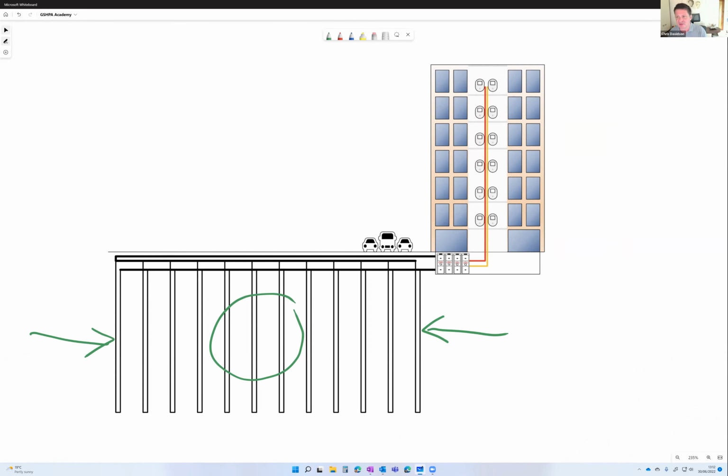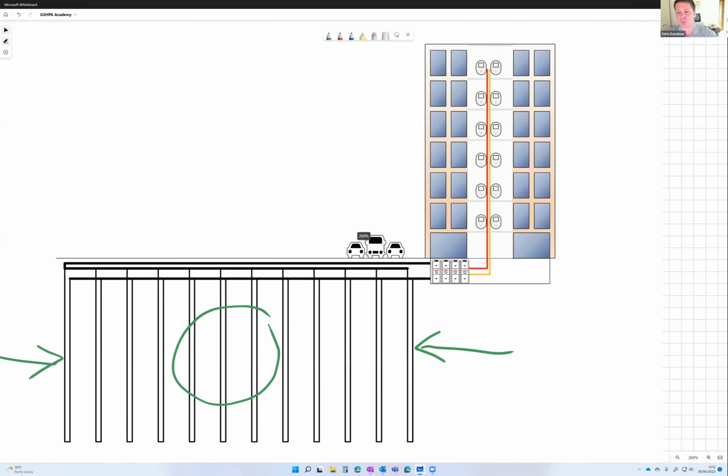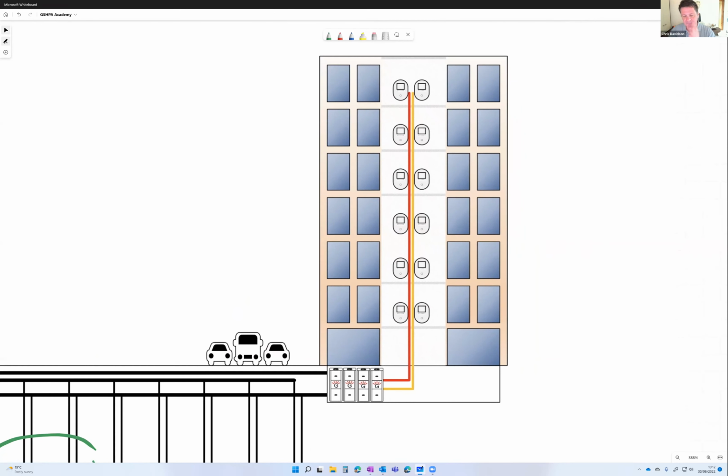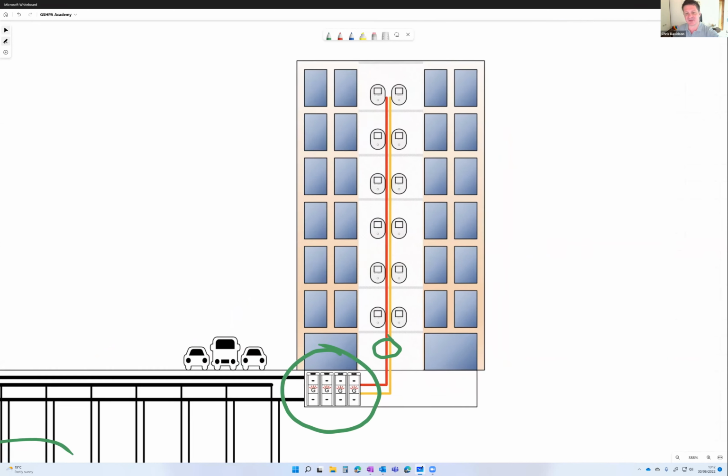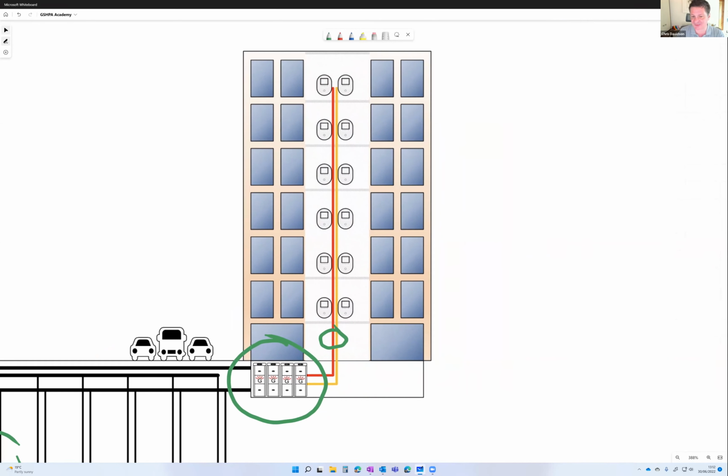I'm going to draw those ground loops today as borehole systems, but again, in previous sessions, there is plenty of coverage of other solutions: mine workings, open loop systems, horizontal systems, and so on. So I'm going to concentrate now on what goes on inside the building. What we have here is some central plant, with heat pumps drawn there, delivering heat up a single high temperature riser, and the heat is being delivered into those dwellings via heat interface units.